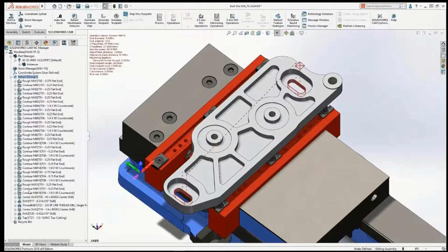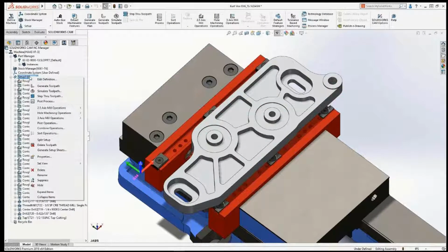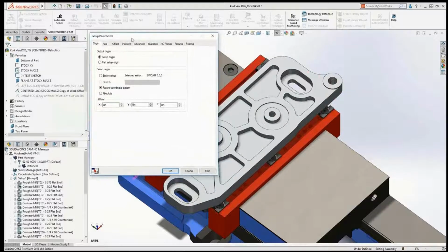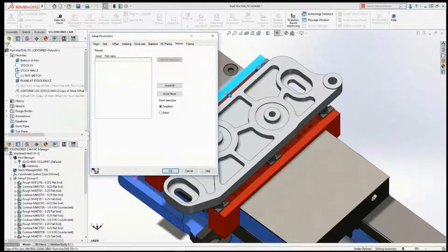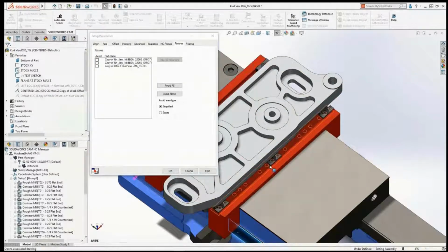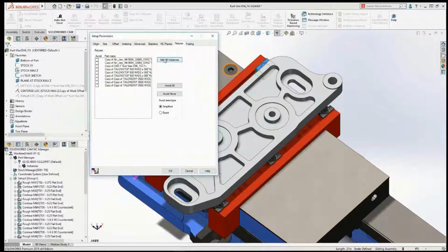One more thing to save cost and avoid more damage is defining the vise component. I'll choose the whole components of the vise which can be in the path of the cutting tool to avoid any collision and failures. Don't forget to use the smart selection tool to save your time.